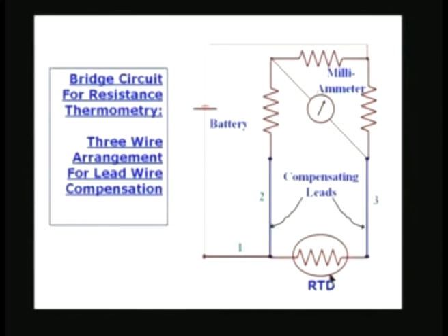That means, when the RTD is at 0 degrees, if I choose such that these two are equal, then I will have to choose this equal to 100. If the RTD is a PRT, PT 100, I am going to have 100 ohms here, for example. Okay. Now, when the temperature changes, this resistance increases, I have to increase this resistance, so that the balance